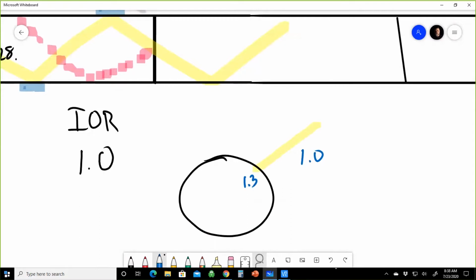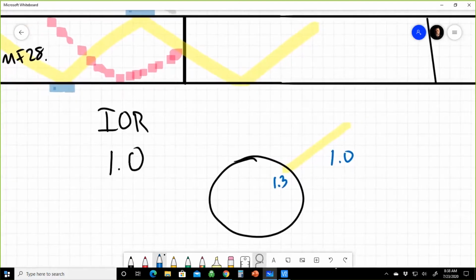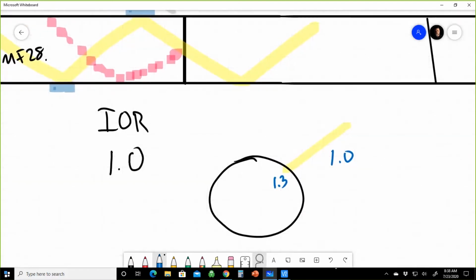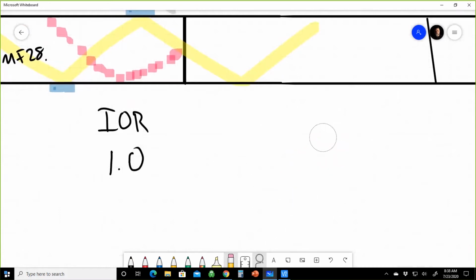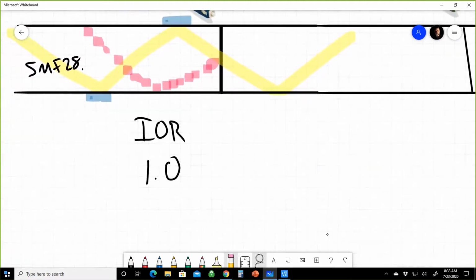And then as soon as it enters water or fiber, it'll have a different index of refraction. So index of refraction is very important to understand if you're going to do precise fault isolation. And so you'll adjust this based on the fiber type or the material type. In our unit, when we go through the setup, I'll talk about it. But in our unit, our default setting for index of refraction is basically G.652D fiber, which is standard single mode fiber, right? There's going to be a different index of refraction for different types of fiber.